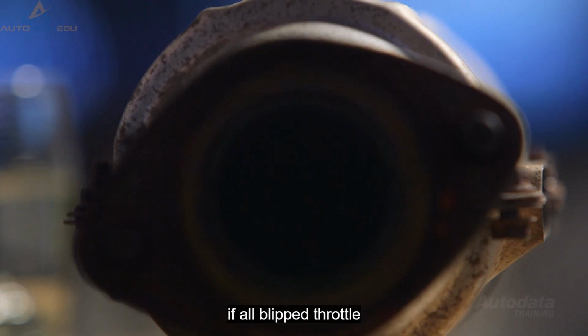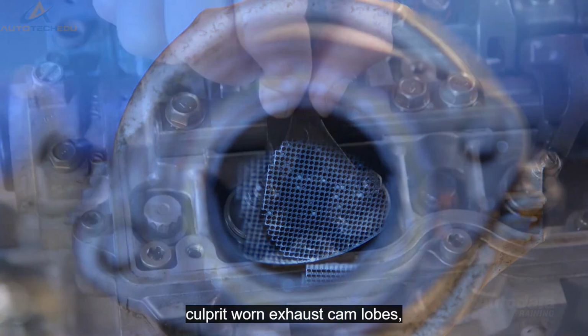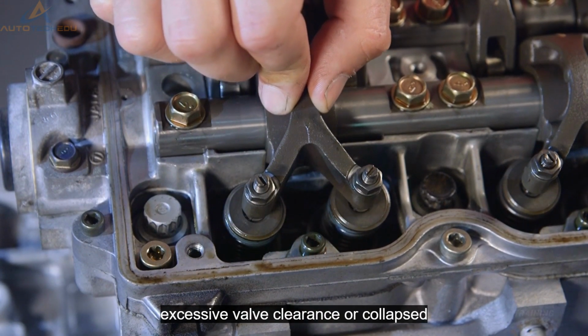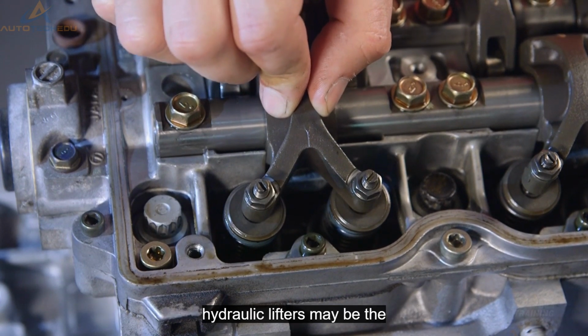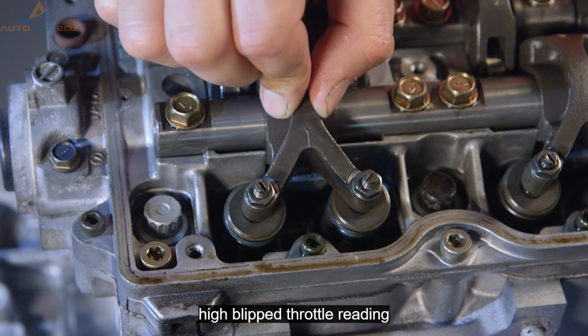If all blipped throttle readings are high, then look for an issue that affects all cylinders. A blocked catalytic converter or exhaust may be the culprit. Worn exhaust cam lobes, excessive valve clearance, or collapsed hydraulic lifters may be the cause of an individual cylinder high blipped throttle reading.